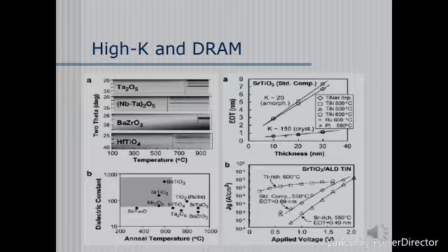As of today, one of the dielectric films with the most promise for these problems is strontium titanate, or SrTiO3. As research proves, it can have a leakage current as low as 100 nanoamps per centimeter squared at 1 volt. The behavior of the crystals of the SrTiO3 has also been researched using X-ray powder diffraction.